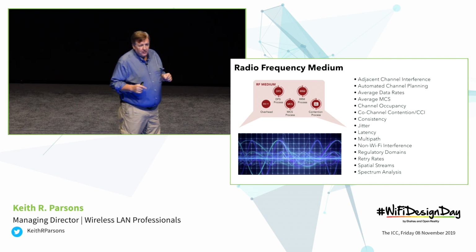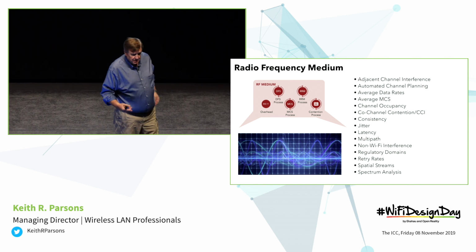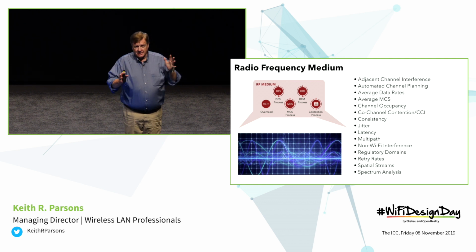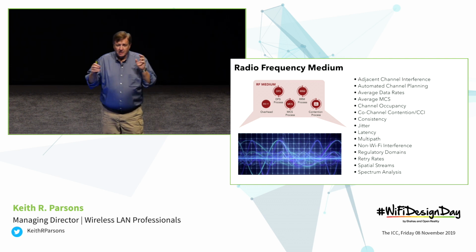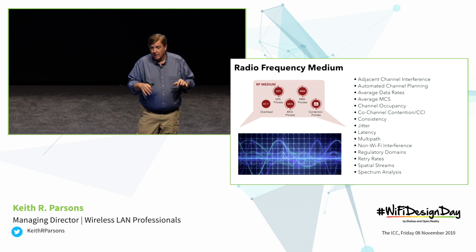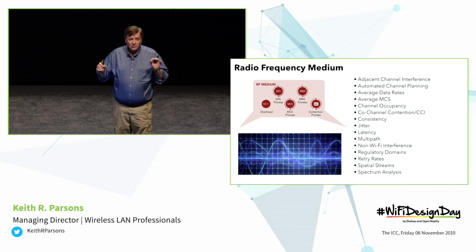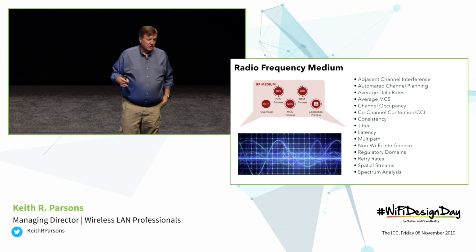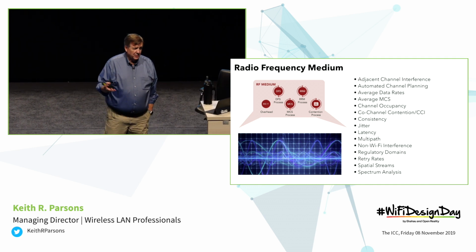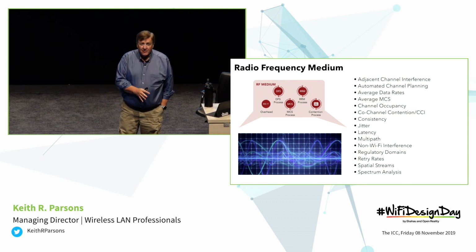And every single frame that ever touches the RF medium has to go through what I call the game. It has a contention process saying, is anyone listening? Oh, no one's there. Is it free time? Yes, I have a little bit of dead air. So now I'm going to take a random number and I might count a random number down, and I'm going to listen the whole time to make sure no one else is talking. No one on preamble detect, no one on energy detect. That's for every single transmission has to go through that, which is why Wi-Fi is not a very good steward of RF spectrum. LTE is way more efficient than Wi-Fi is. Wi-Fi is free.